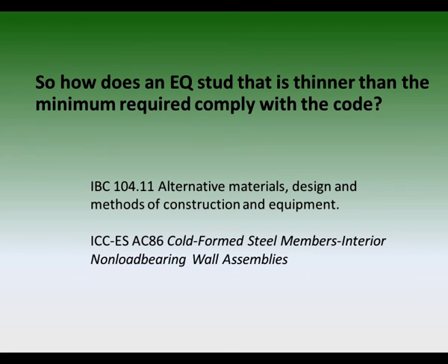As an alternative material design or method of construction, EQ studs are approved under Section 104.11 of the IBC. EQ studs are typically certified through third-party testing in accordance with ICC-ES AC86.